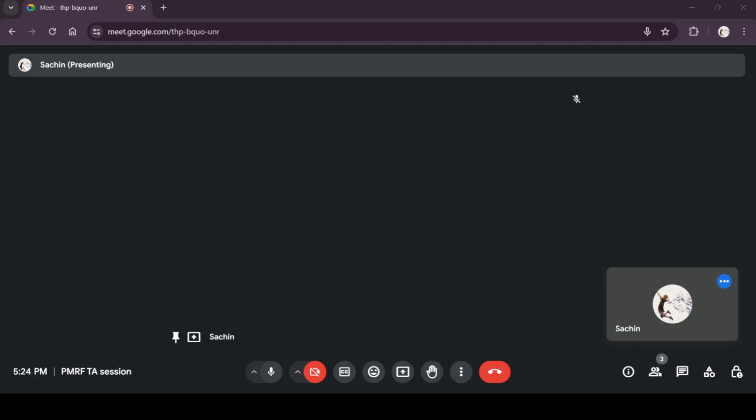So you have all the minterms here. You can see A bar, B bar, C bar is minterm 0, A bar, B bar, C is minterm 1. So these are minterms 2, 3, 4, 5, 6, 7. So all these minterms, how do you connect them? You connect them using a diode. So the way this diode based ROM works is, wherever there's a diode, that particular minterm is present in your output. Also, if there are multiple diodes, then they will be all together. So that's how this circuit works.